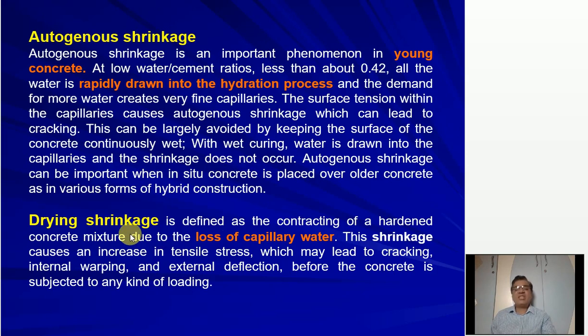Well, what is drying shrinkage? Drying shrinkage is defined as the contracting of hardened concrete mixture due to loss of capillary water. This shrinkage causes an increase in tensile stress, which may lead to cracking, internal warping, and external deflection before the concrete is subjected to any kind of loading. That means the cracks or the external deflection occur even when the member is not subjected to any loading. So this is due to drying shrinkage. Well, now how to get the autogeneous shrinkage strain and drying shrinkage strain, that we'll see in the next slide.